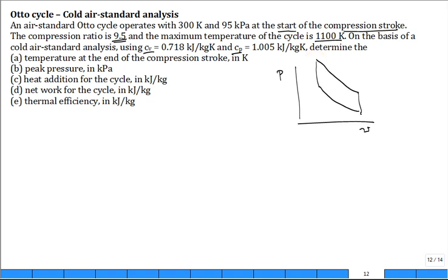Something like this. We want to stay with the textbook's numbering system, which is helpful and very common. Start at 1, and then go. Also, you really only have V at bottom dead center: V1 is equal to V4. And you only have V at top dead center: V2 is equal to V3. True? Only really two specific volumes. And the compression ratio, R, is a number greater than 1. It's 9.5 for this problem. R is V sub 1 divided by V sub 2. Is that true?